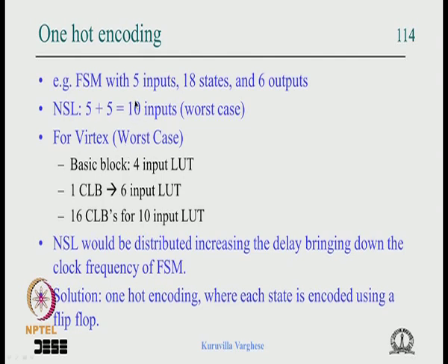Even if there are really 10 inputs for some decoding, that may not require a 10 input lookup table. One can cascade, but assume the worst case happens.